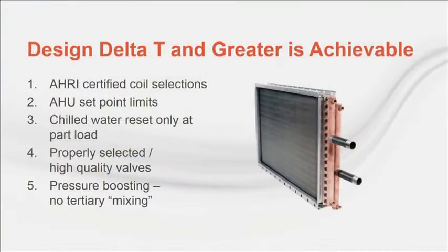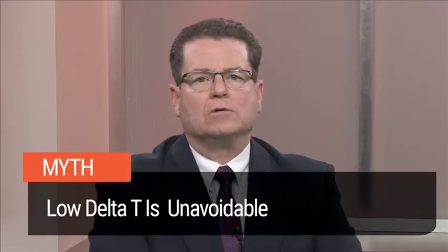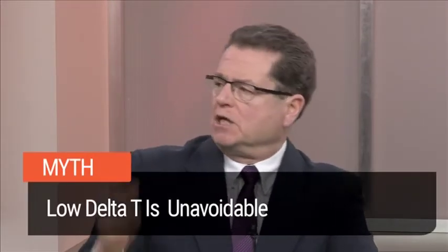We would suggest that maintaining system delta T at or above the selected value should be relatively easy if the system includes properly selected and sized AHRI certified coils, set point limits, high quality control valve selections, and proper controls commissioning. Low delta T unavoidable? We don't think so. Jeannie, this myth is busted.